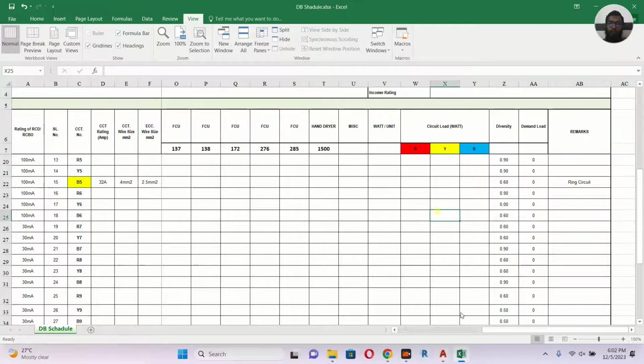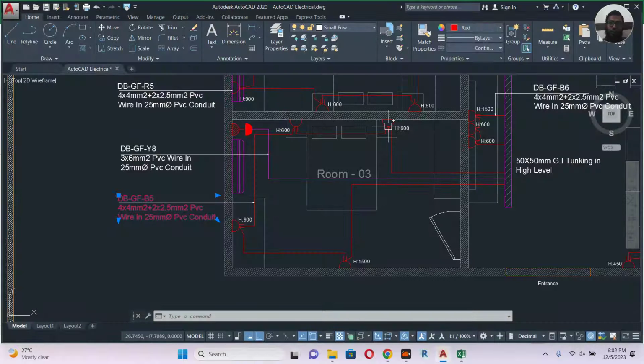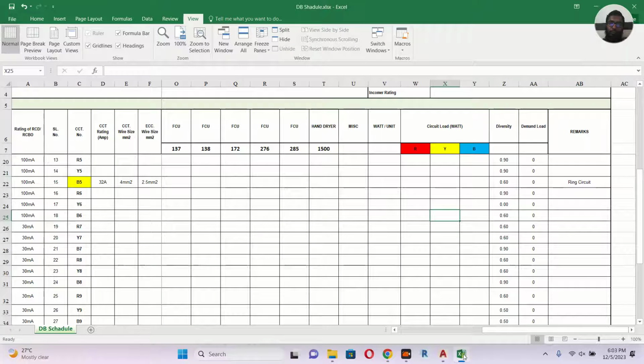So I think if you see the drawing, you will see here this is in and return also. That's why it is 4 by 4 mm, because 2 by 4 mm coming like this and return like this. Then actually here is the 4 by 4 mm. That doesn't mean 4 mm, 4 cables. Actually 4 plus 2, 6 cables, meaning 3 here, 3 here. I hope if you go through my video from the beginning, you will understand this one. I don't want to repeat that one.